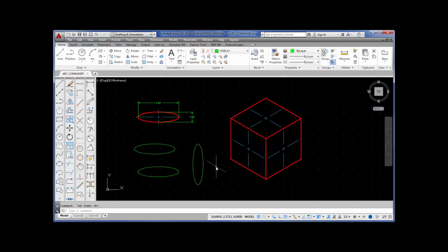Notice that your grid is not only dots, but it's also oriented in isometric, vertical, and this is a 30-degree line, as a matter of fact. More importantly, look at your cursor. It is oriented in isometric. I also want you to notice that if you press function key F5, it will toggle your cursor. So watch the cursor. F5, F5, F5. It is toggling these three center lines.